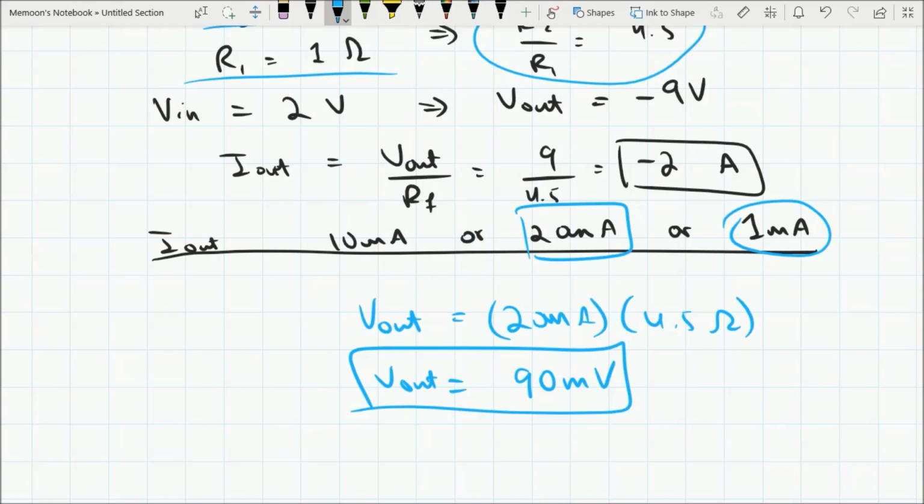So we have to be very careful while selecting the combination of these resistors. Yes, in some cases you can give even attenuation to your input voltages. An amplifier is a circuit that provides gain. The gain can be more than 1, the gain can be less than 1. In cases of less than 1, we call it attenuation, but still it is a gain of, let's say, 0.1.